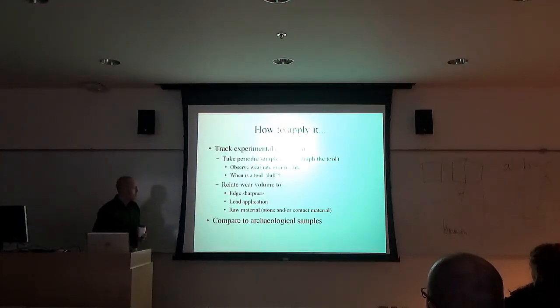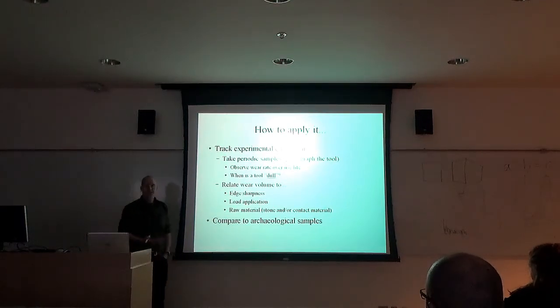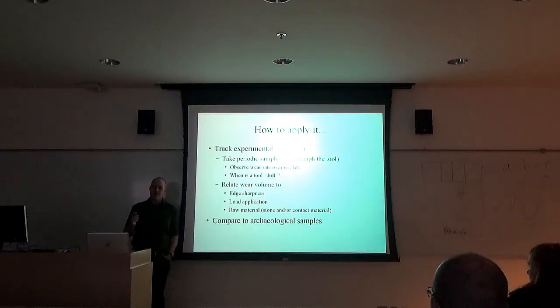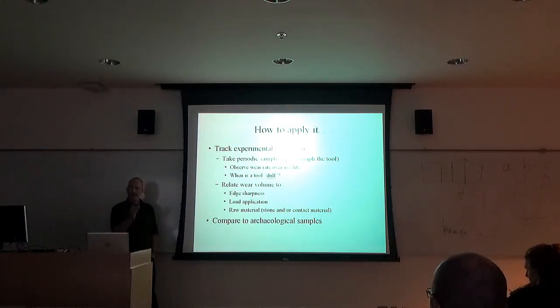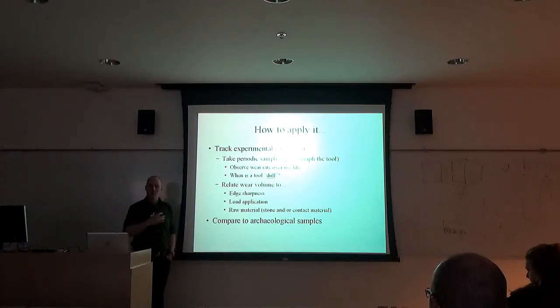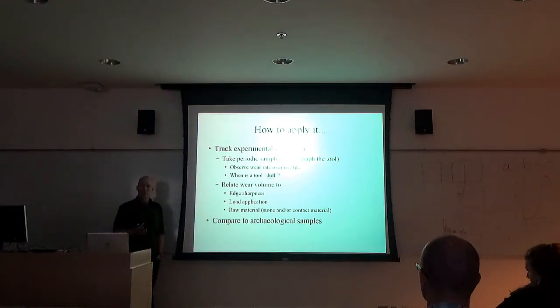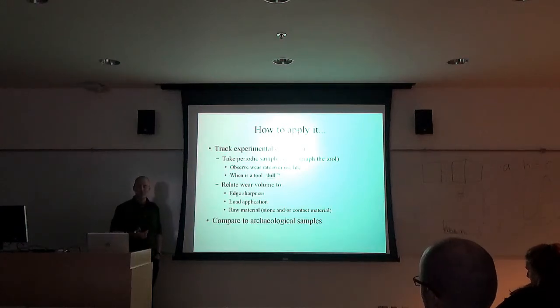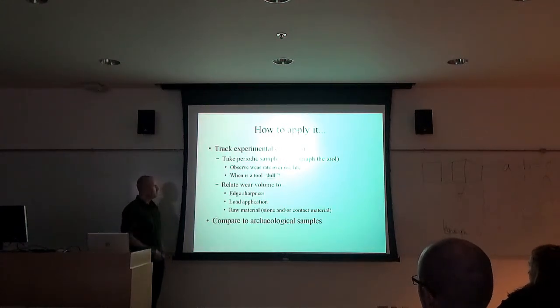So the way to do it then is to do experiments. Record the wear, apply it to the wear index, so you can actually use your peak and integral wear to scale up or down the wear index for different users, so you can actually control for user strength on the same task. And then see what it looks like. Where is the wear happening? What is the intensity of the wear? When do you stop using a tool because it's no longer practical to use? You know, when is your sharp knife as impotent as a spoon?